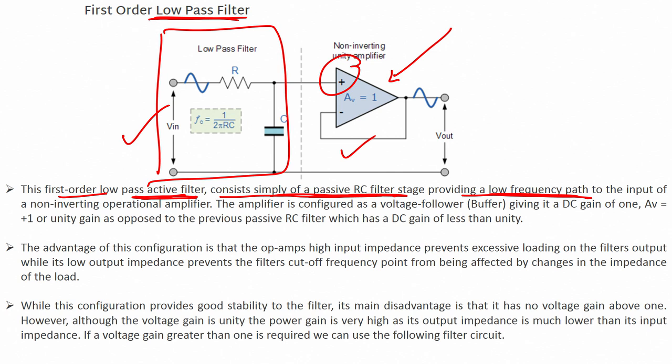So, this is the RC filter, and whatever the output is here, VO, this output is with respect to ground, right. So, this is ground. I have told you earlier also, if you do not see a ground, assume that there is a ground. With respect to ground, this is the voltage that is generated, and it is fed to the non-inverting terminal of the operational amplifier.